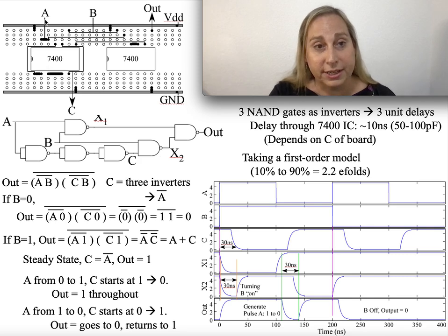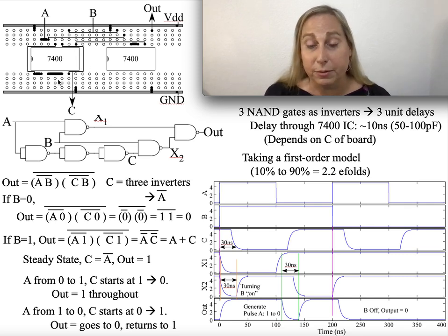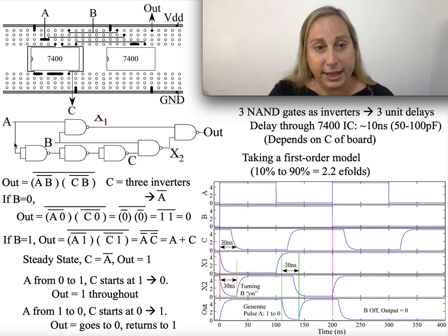Well, what does it look like? One of the interesting things, if I look at A, is that I've got a double connection to an output, and then another double connection to an output, and another double connection, and that gets into the circuit. That's 3 inverters in a row. Kind of interesting, actually. It's almost like it's trying to make a delay. That's A, and it's 3 inverters here. Then I also have A and that inverse, whatever that term is, which I'm going to call C for the moment. These both feed into NAND gates that have this terminal B.